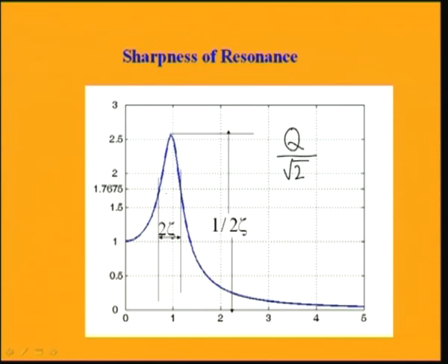So, at that amplitude let me draw this line. So, you can see that it is cutting at 2 points. So, I have to find this magnitude or these frequencies, at what frequency this is occurring. Let this frequency be omega 2, this frequency is omega 1. So, let us find the range of frequency at which we should not operate this system. So, I have to find this omega 2 and omega 1.